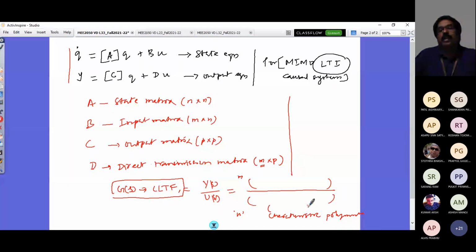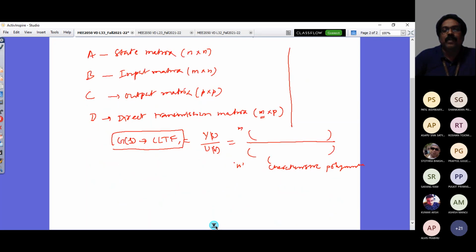So when I make that equal to 0, I make a condition that I look at my system without an input. I just look at my system with this initial condition and giving some disturbance. And that kind of analysis is what is called an eigenvalue analysis. That is essential for our stability analysis, right? Remember that point. So now let us continue with this representation of equations.